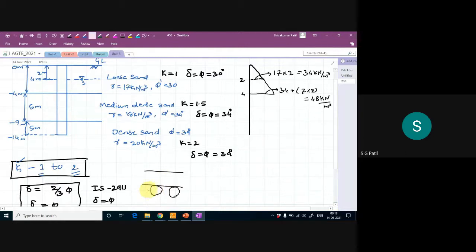Okay, so here also this pipe and soil will be there. So here also the soil arching concept will come into picture. So you have two options here. Either you take it, because this is a still debated topic. Some people will tell you in the field you won't experience the soil arching, but some people will tell you to consider the soil arching. So if you solve it with any method, that is also fine.